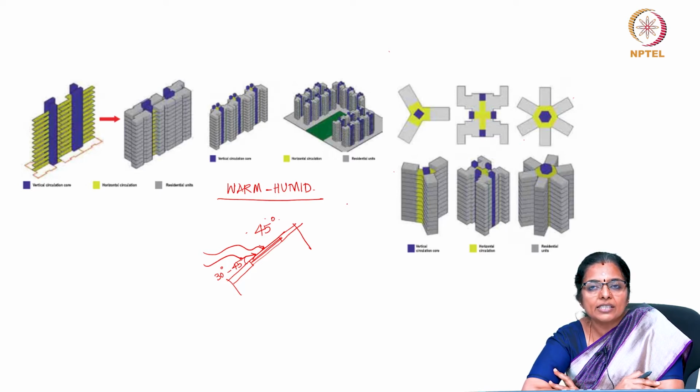The compromise on how large that opening should be, to allow breeze and to prevent solar radiation, must be arrived at. You can also look at diverting the wind direction by means of vegetation and structural arrangements, such as having shrubs at a particular height or small parapet walls or something like that.